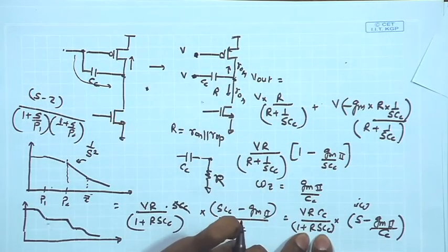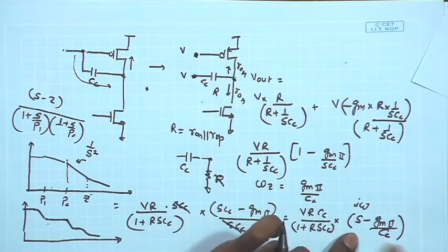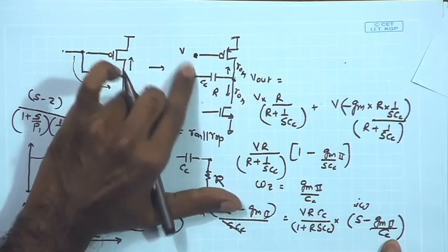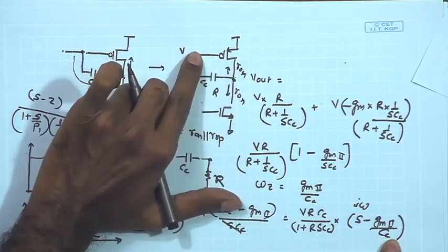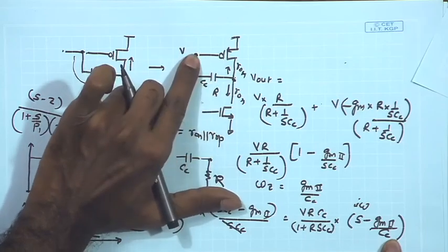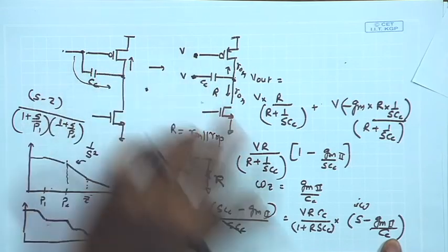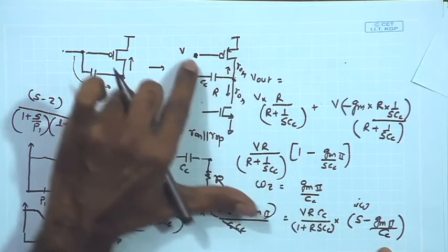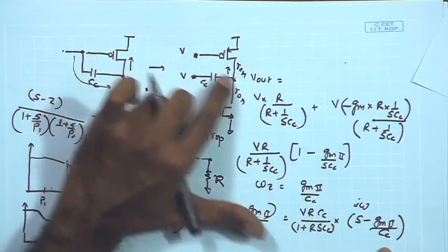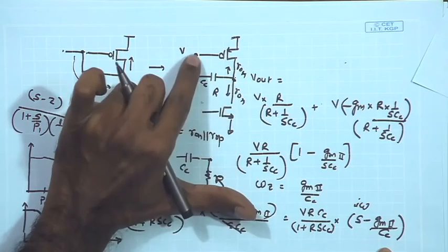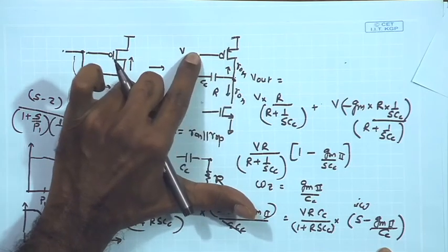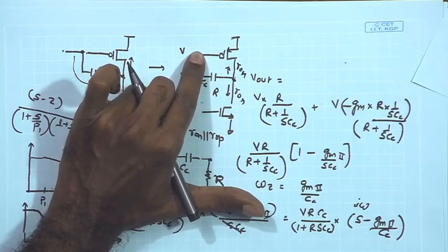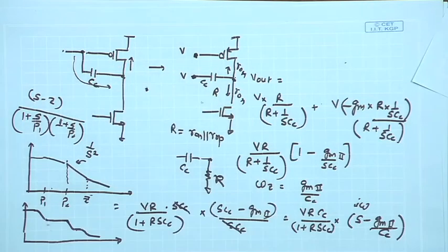Here that assumption has not been taken. So, here, just to show the effect of the 0, and without considering the degrading impedance over here and the drain and gate getting short circuited, those things have not been incorporated over here. So, this is just using first order equations to show how the 0 is appearing, without considering the other effect where the CC connecting the drain and gate is effectively getting short circuited, and it is reducing the impedance, which is pushing that pole to high frequency.